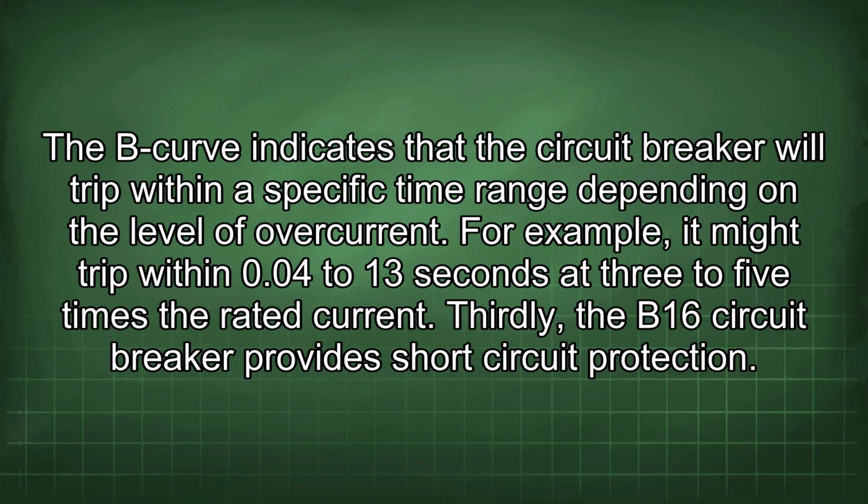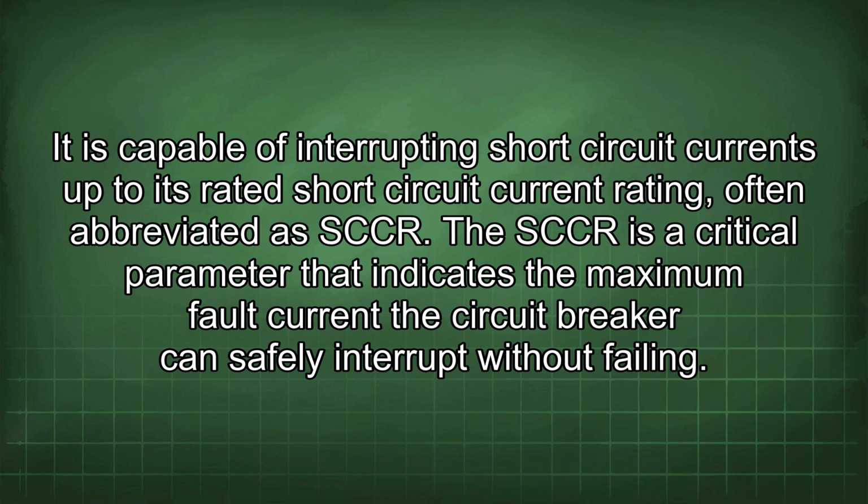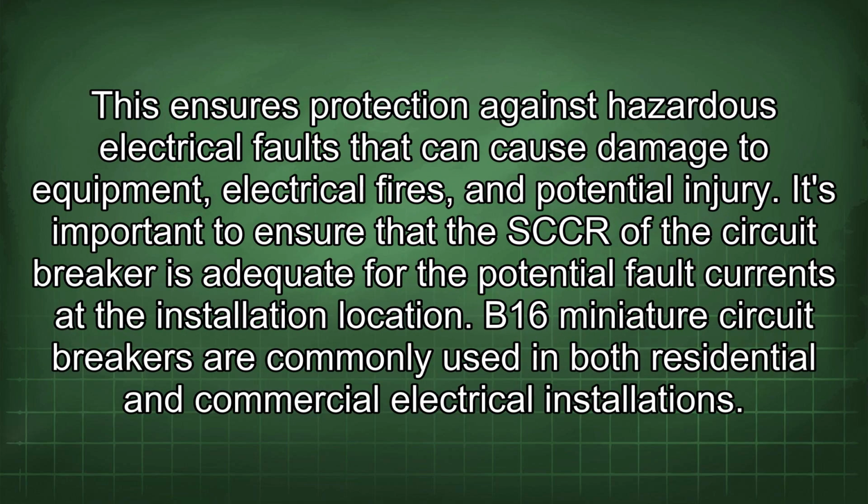Thirdly, the B16 circuit breaker provides short-circuit protection. It is capable of interrupting short-circuit currents up to its rated short-circuit current rating, often abbreviated as SCCR. The SCCR is a critical parameter that indicates the maximum fault current the circuit breaker can safely interrupt without failing. This ensures protection against hazardous electrical faults that can cause damage to equipment, electrical fires, and potential injury.